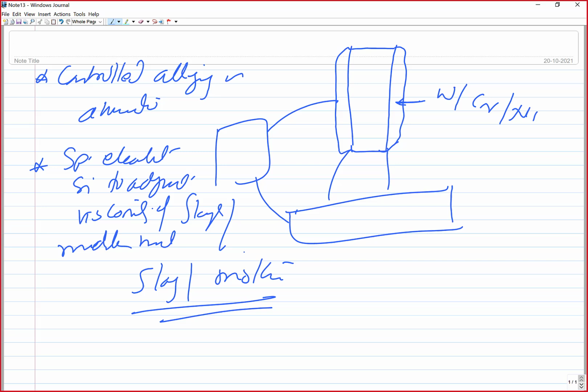Another important role is that these coatings act as an insulator. So even if the electrode accidentally touches another conducting metal, short circuiting is avoided. The coatings act as an insulator, so direct short circuiting and closing of the circuit by the electrode due to accidental touching with other metals is avoided.